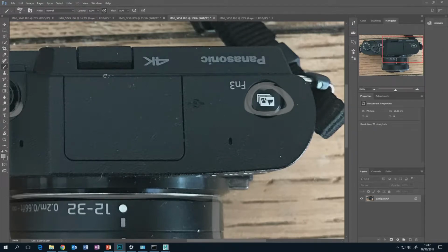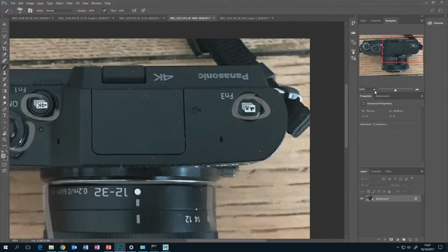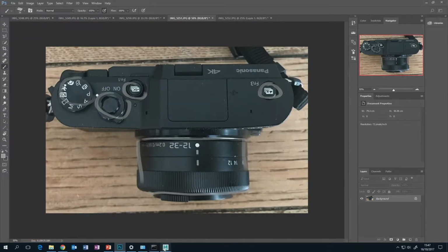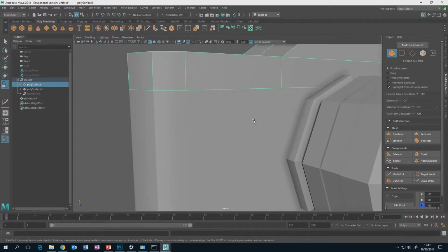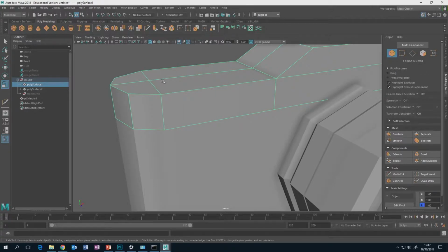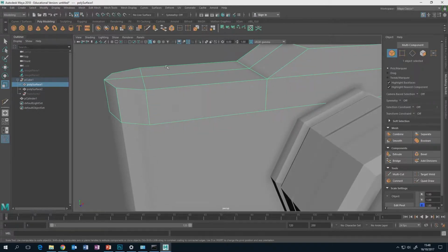So any kind of crease or seam that you have, you ideally want to put some kind of bevel where they meet up. If you do that, you'll find that your models just look that bit more pleasing. They look more realistic. They don't look as harsh because when they're lit, the light can play across that indentation rather than just have completely different values.